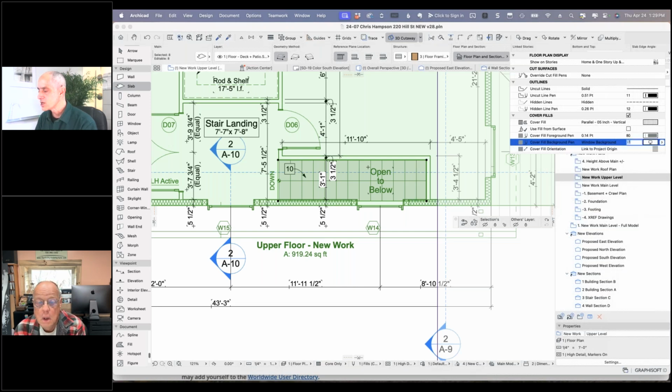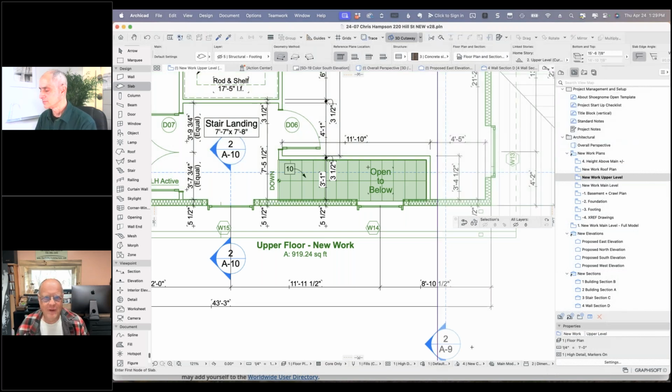Now you can see it just covered up some stuff here, there, and cover fill parallel. So is this supposed to have a 5-inch? I use that for wood flooring in some views, like my schematic floor plan views. And so there's a model view option that's hiding it. And I'm not sure I've got control of it quite the way I meant to.